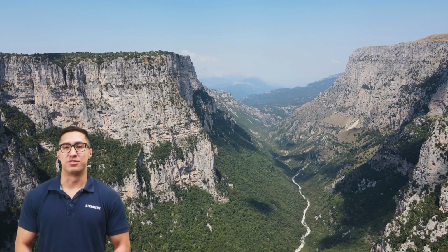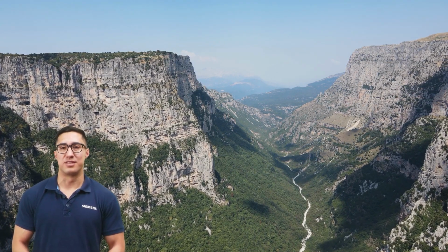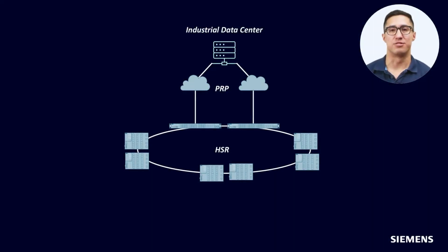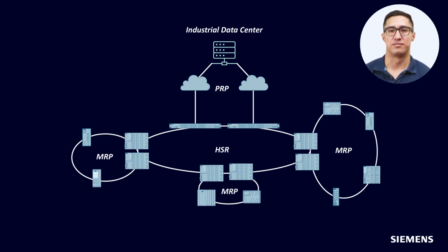Let's discuss new innovations from Scalance, HSR, PRP, and MRP redundancy mechanisms. Let's look at the high-level network topology of HSR and PRP. With Scalance's latest features, you can couple MRP rings to this HSR ring, bumpless technology. A network disruption up to 200 milliseconds in one MRP ring won't affect others due to HSR technology. This helps network design. Use PRP or HSR upstream to prevent faults downstream. MRP works well downstream, supporting more devices with MRP functionality.